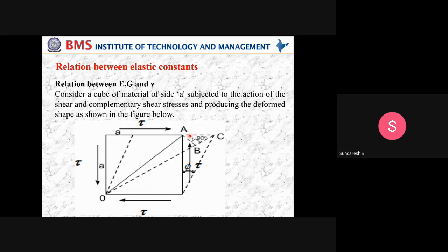I have already told you the strain is very small. The angle ACB is 45 degrees. So now this is 45 degrees, and 45 degrees is nothing but cos 45. If I write cos 45 for this, it is the adjacent side divided by the hypotenuse. Now what I want is BC. Am I right?